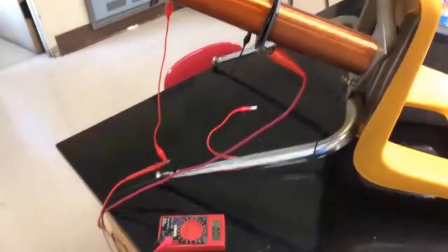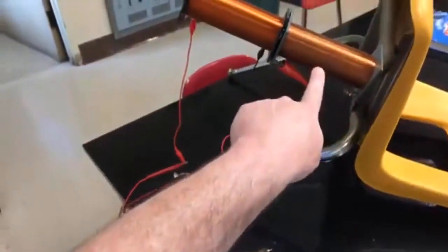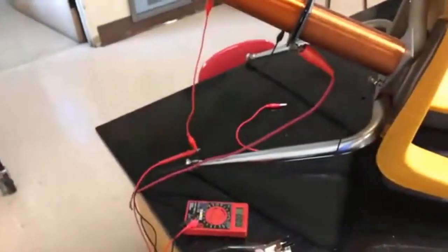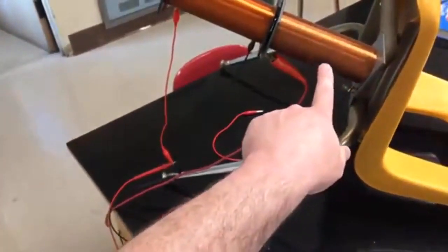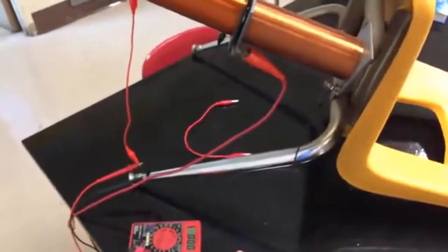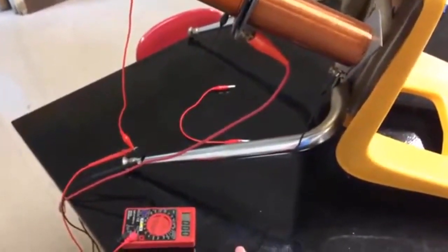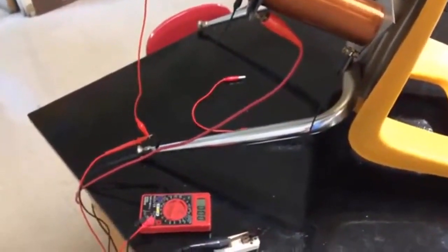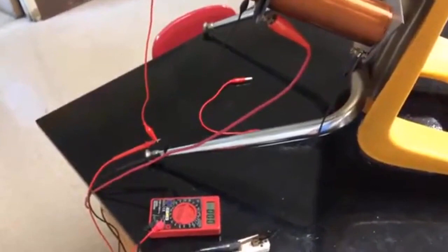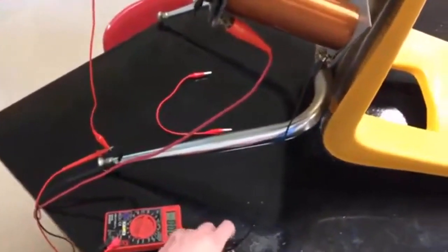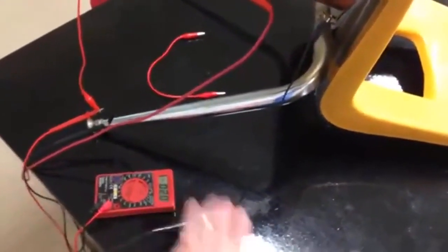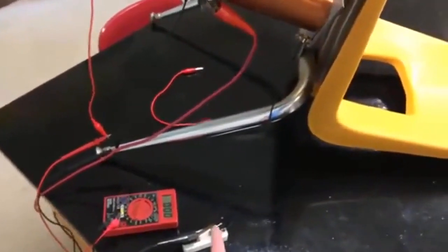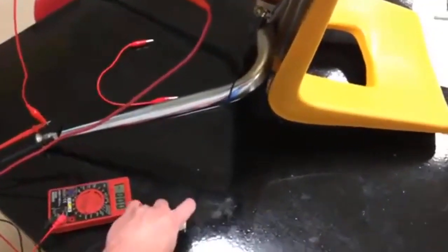So right now, with no current inside the primary coil, there's no magnetic field inside the secondary coil, so we see nothing. If I change the magnetic field to non-zero by turning on the primary, we briefly, during the time of change, see electricity in the secondary. But then it goes back to 0 because it's not changing anymore. It's like you've shoved the magnet in and haven't pulled it out yet. Going back to non-zero briefly gives us electricity again, but then it goes away. So you'd have to keep turning this on and off.